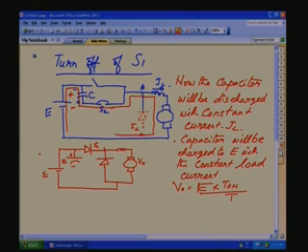From this circuit, when T1 is turned on, the voltage across the C was this one, plus and minus here. Now due to the resonance charging, it will come to the negative voltage here.